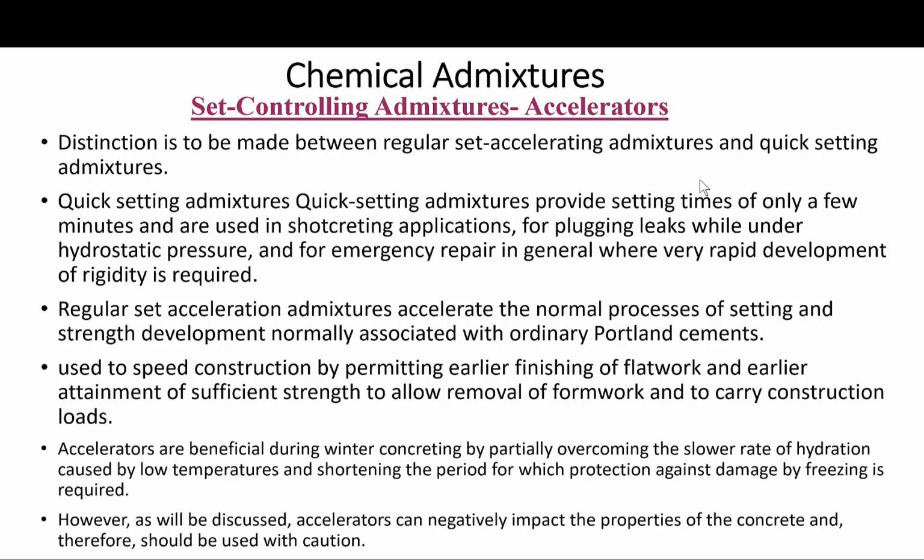Accelerators are beneficial basically during winter concreting by partially overcoming the slower rate of hydration caused by low temperatures and shortening the period for which protection against damage by freezing is required. When you place concrete in freezing environments, there are many things you have to do, one of which is to provide protection in order to make sure freezing does not occur.